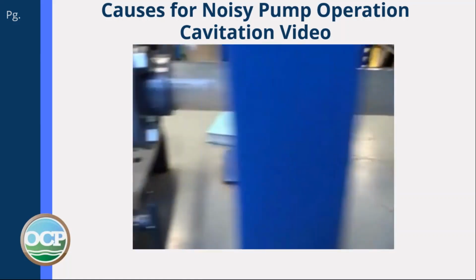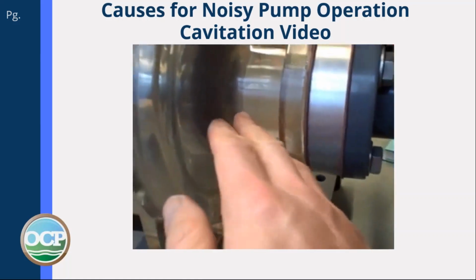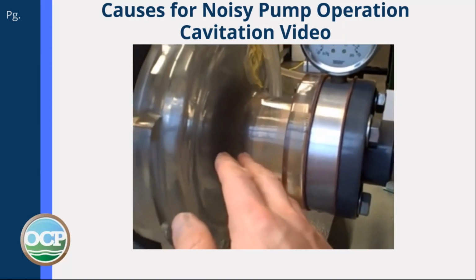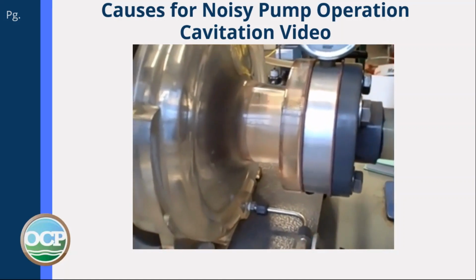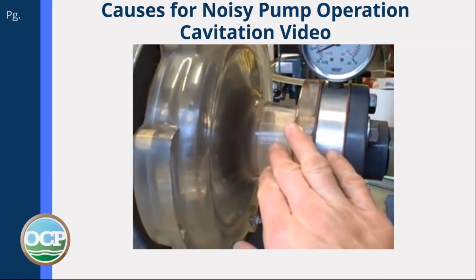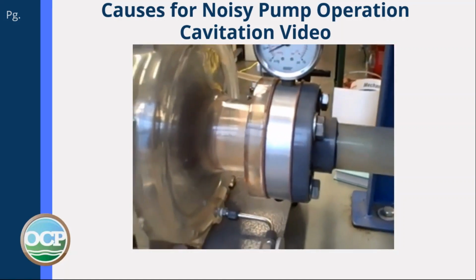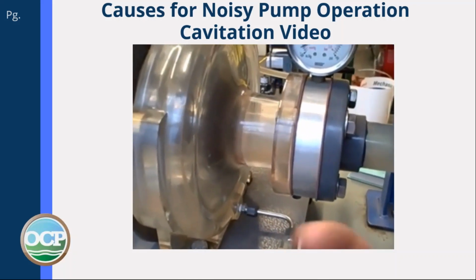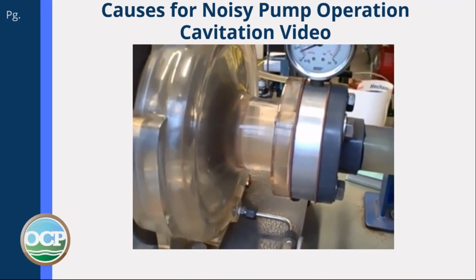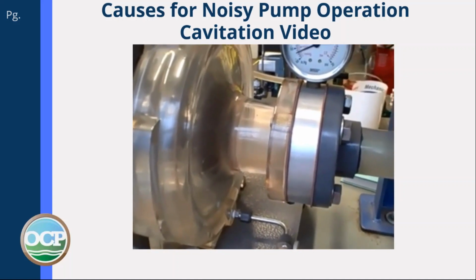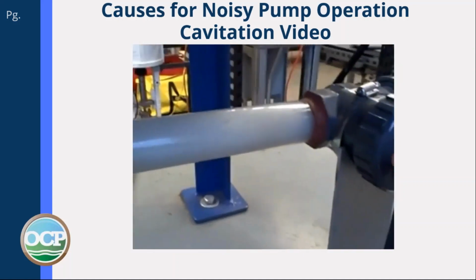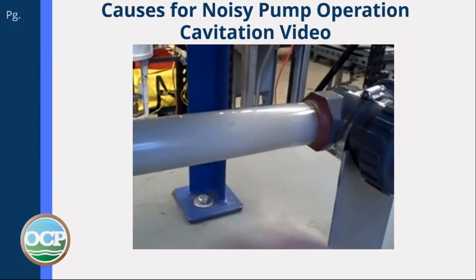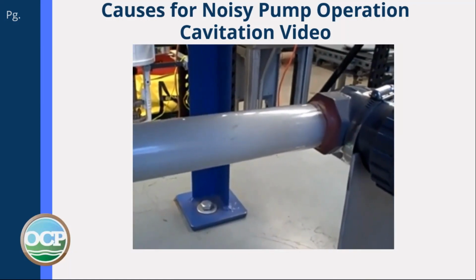You can see it happening here. We can also see some bubbles here in the scroll casing of the pump. Cavitation is very destructive, especially upon metal surfaces. The acrylic surfaces here seem to handle it a little bit better, but with metal surfaces that don't give, it's very destructive. The metal becomes pitted by the high pressure jets formed by the collapsing bubbles. So I just want to illustrate what cavitation looks like in an acrylic tube and what it sounds like.